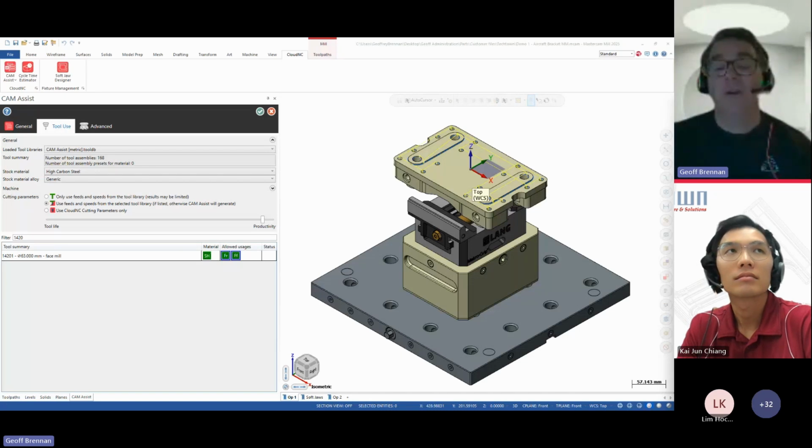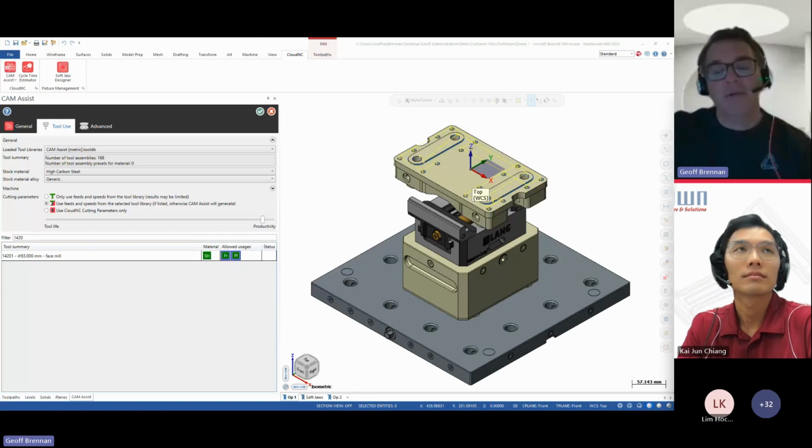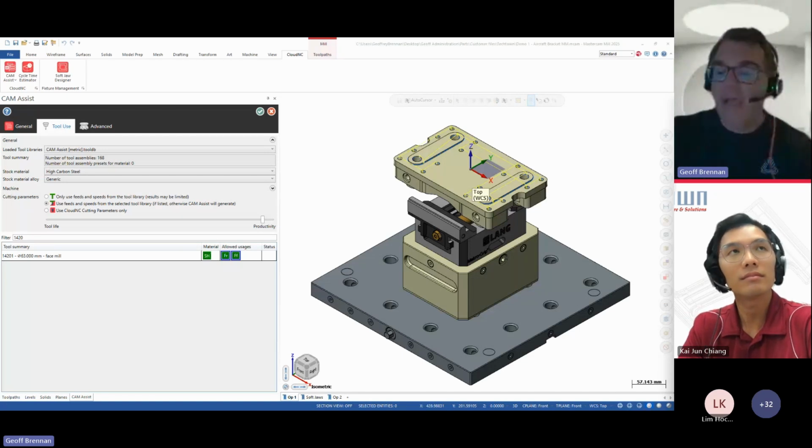For instance, on a flat finishing operation, I know I'm going to use an end mill, but I know that stick out of that tool cannot be greater than 4 times the diameter because I'm going to experience too much tool deflection and I'm not going to get a good surface finish. So I'm going to try out the next tool. And it's running through that millions of times on each part.